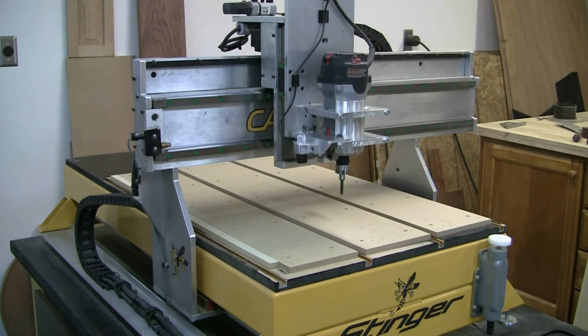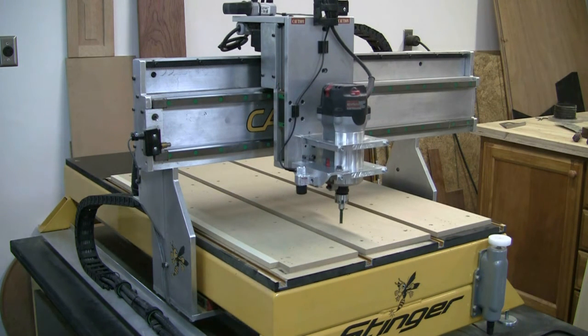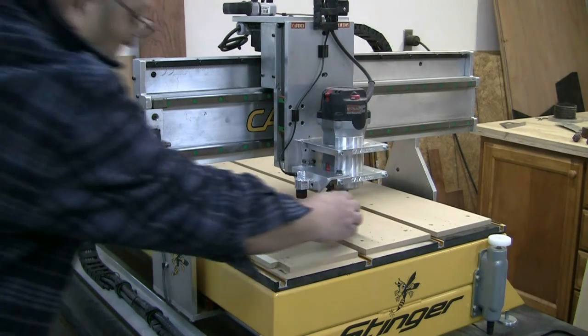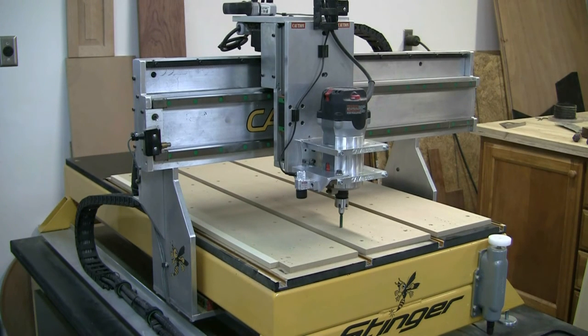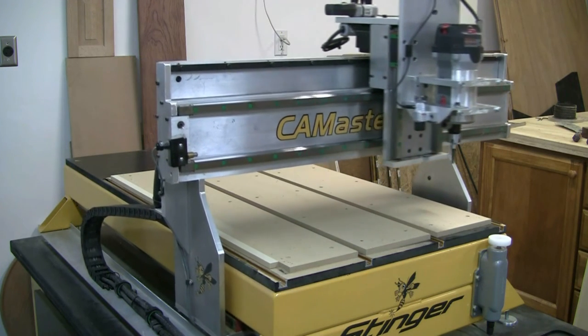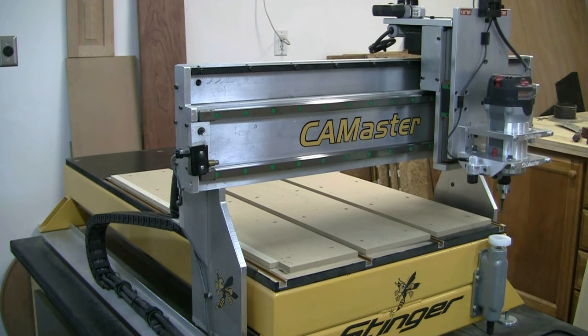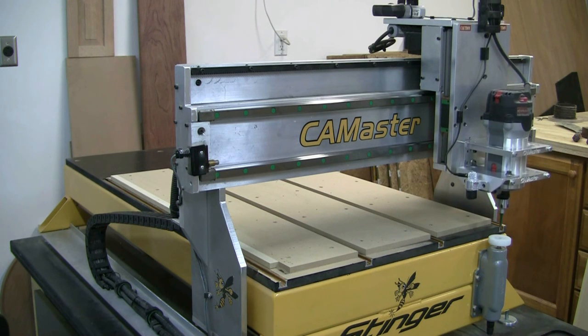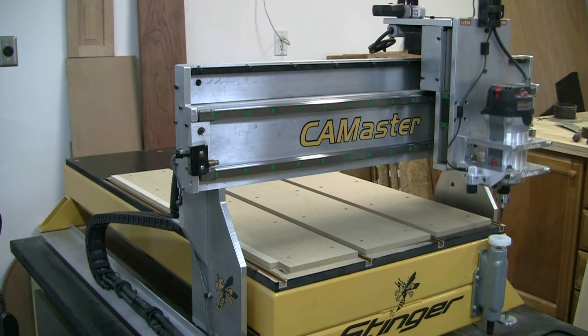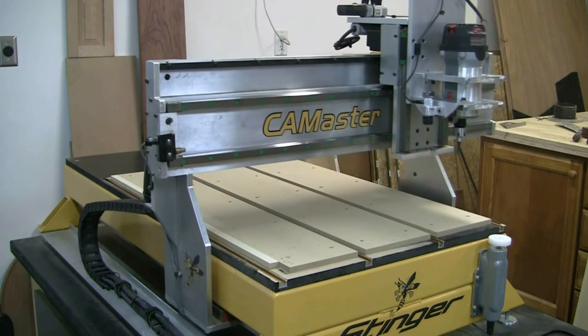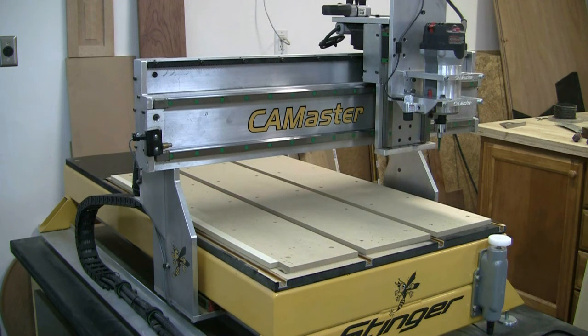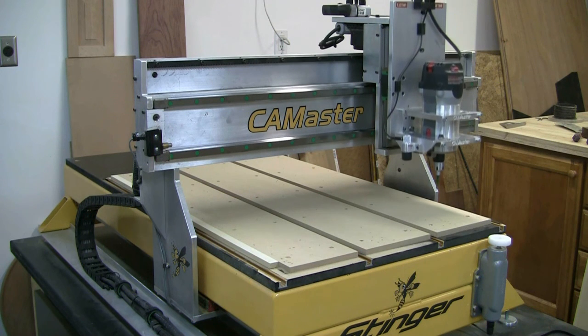1 second. So I would type in Z.4. So now I'm back on the top of my spoiler board again. The router bit rotates. I have to click calibrate switch again to get it back to its original Z0 on the table. So now we should be back to normal. Z0, enter. So now I'm back on the table.